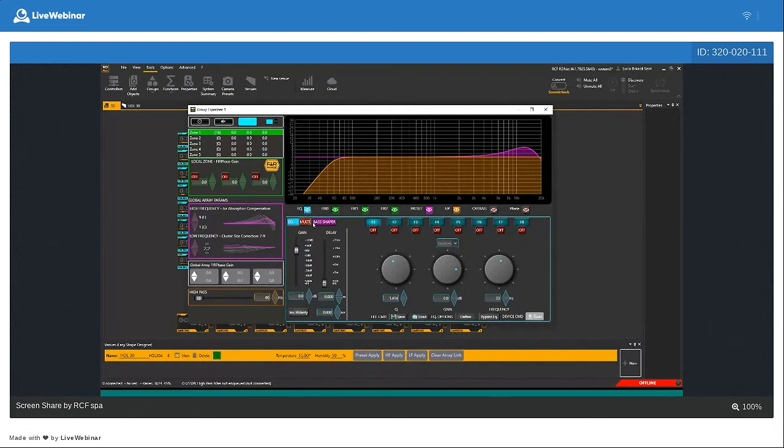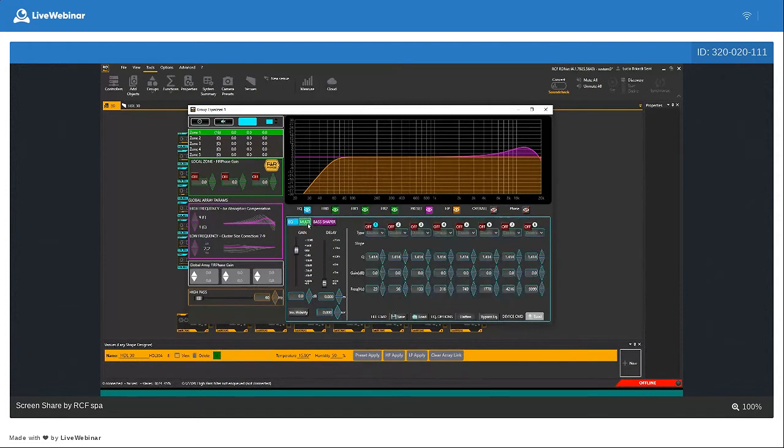At this point, if I need to make some adjustment, talking about equalization, for example, my system is a little bit boxy, something like that. So I can enable one band of my equalizer, and I can reduce the box's frequencies, for example, at 750 Hz by a couple of dB, if it is needed. But I am doing something without sense in this moment, just to give you an idea.